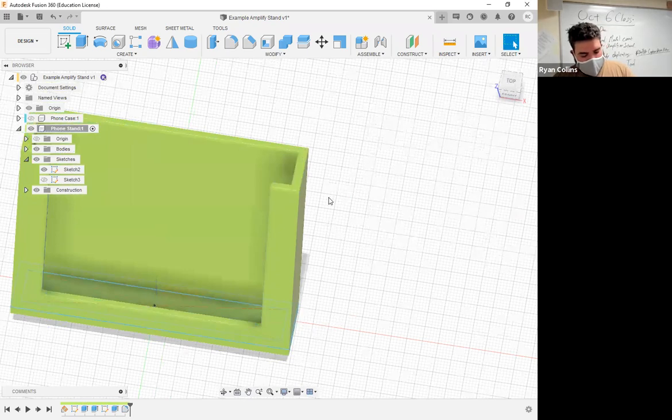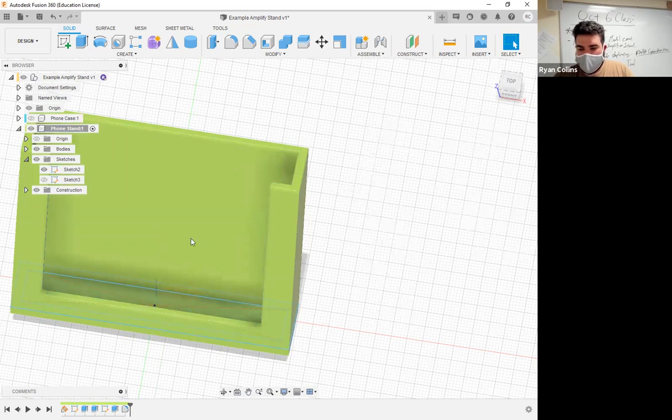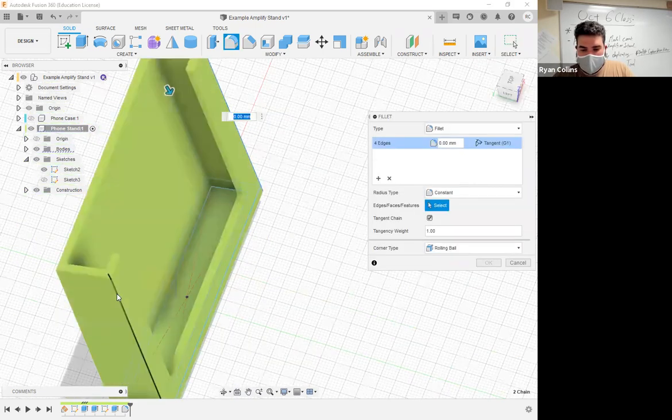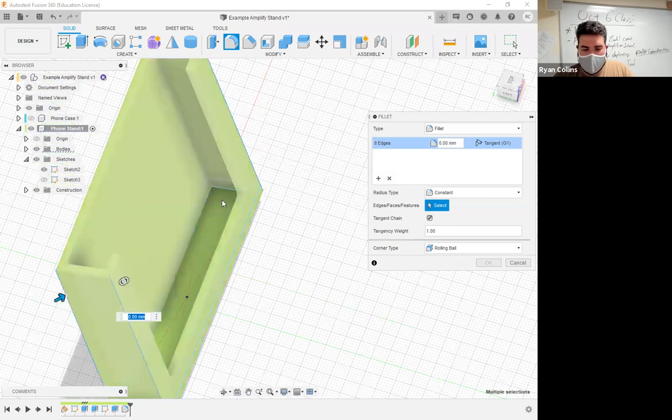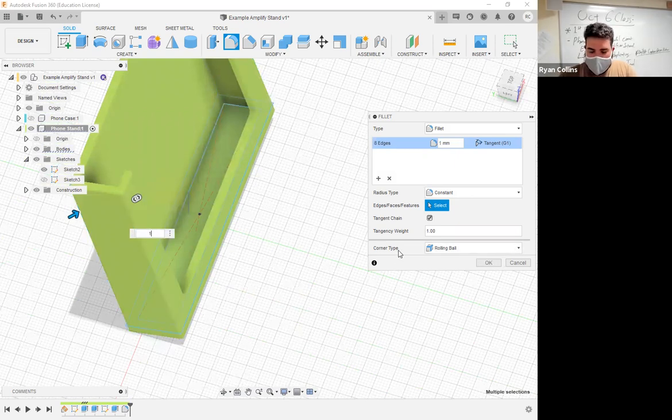Okay, do another one for the edges, repeat fillet. Right click, repeat fillet, do that one. Now, as I'm doing this, if this runs into an error, I will note that I need to put this fillet before the one I just did. Let's see what it does here. No, okay, cool, that's fine. Just because the tops were already rounded. If it's trying to round a thing that's already been rounded, it might cause a problem.